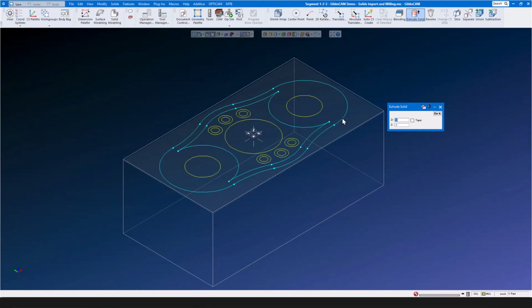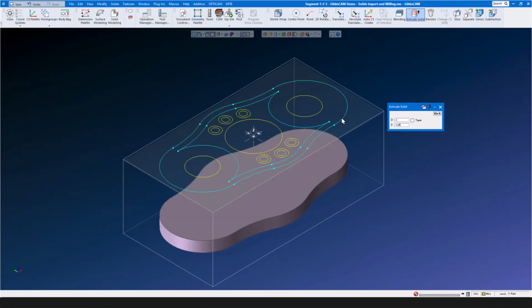Let's first extrude this outside shape down 1 inch and all the way down -1.25. With a simple click of a button, we took a 2D shape and created a 3D drawing out of it. We now need the intermediate step. Let's flip these 2 arcs over using the reverse arc command, which is Control-T.